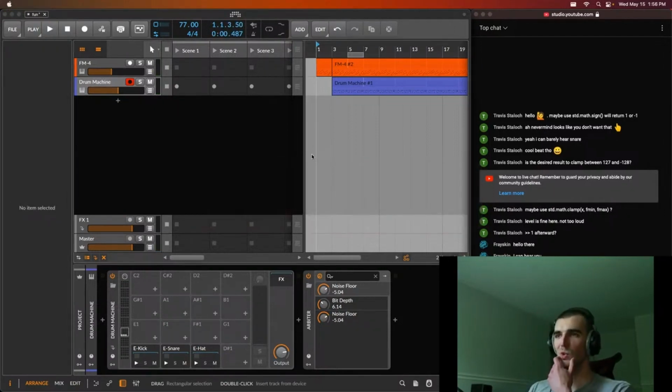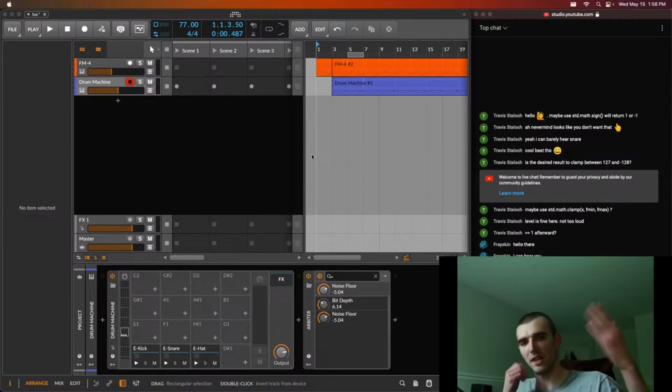What else can we do in bitcrushing land? I did want to do a downsampler, a very crappy downsampler where we just discard every other sample, or we discard every 4 samples or something, and you'll just have some sort of integer that defines the downsampling level.